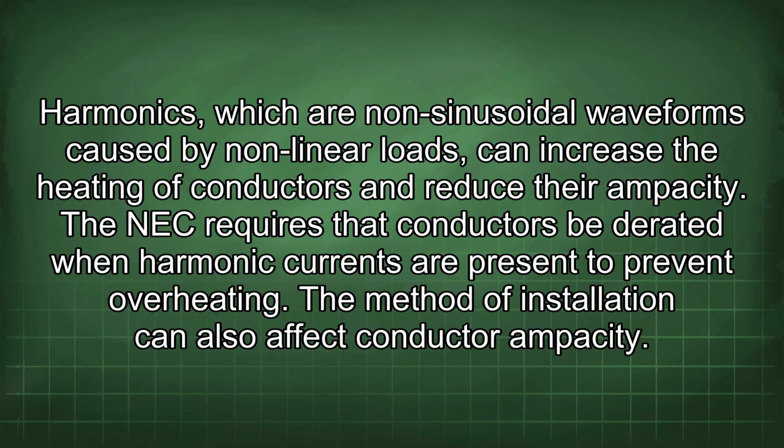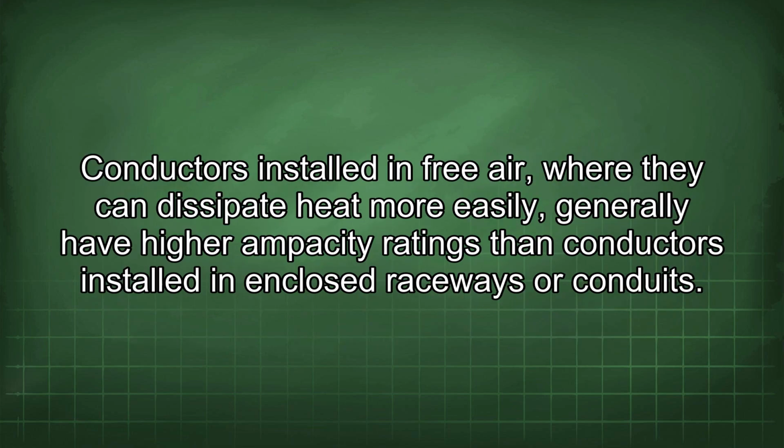The method of installation can also affect conductor ampacity. Conductors installed in free air, where they can dissipate heat more easily, generally have higher ampacity ratings than conductors installed in enclosed raceways or conduits.